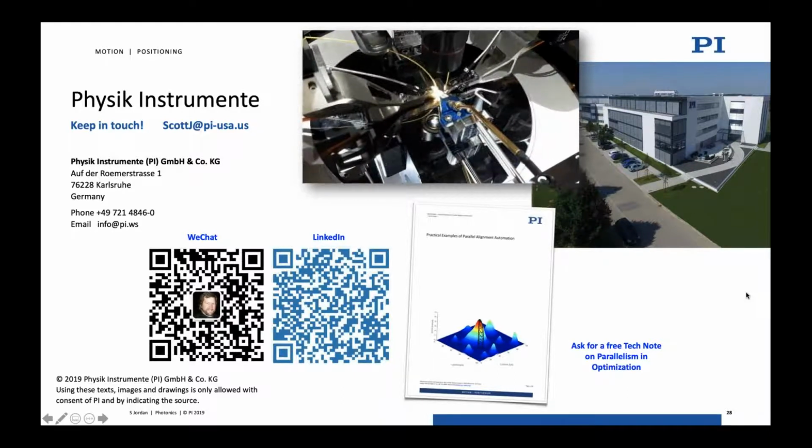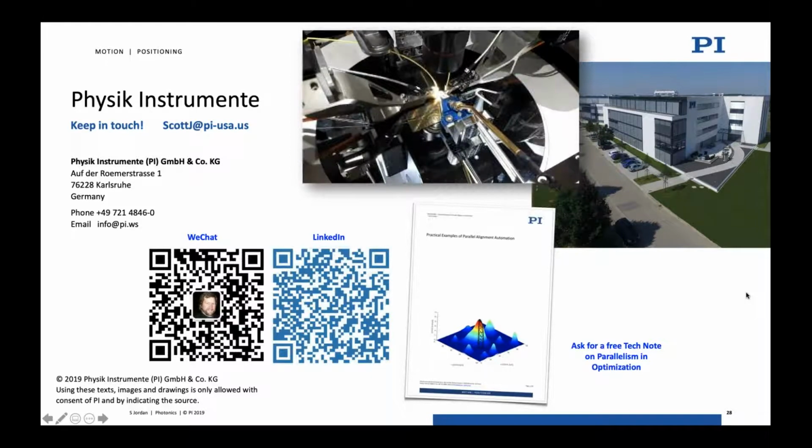They're connected together. These have various names. I've heard them called omega devices and things like that. It's basically 2 of the channels are dedicated to alignment. So light goes in one and it comes out the other. So there's only one detector. One source comes through, one output. So now I need to align in X and Y and theta Z at a minimum to line up that array. But I only have one detector. That's okay. Our system looks at the modulation caused by both of those processes and separates them. It's automatic.